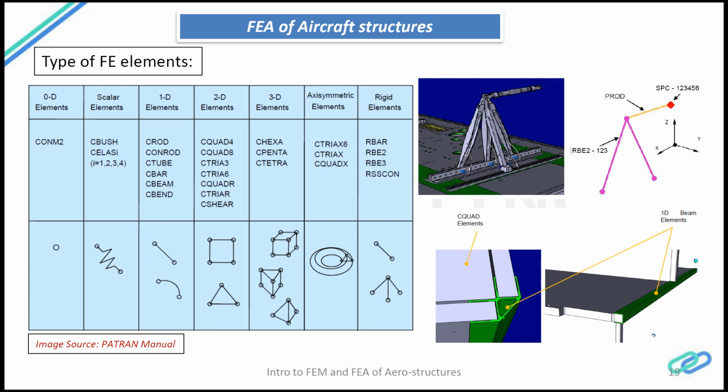What you are seeing is the top attachment, where you can see this is a top panel and there is a beam running throughout the length, which is a steel beam or a machined aluminum beam. And there is a series of struts, and finally this strut, going from the side struts, will be attaching to the aircraft interface, which is on the ceiling of the aircraft where there will be a lug. The other end of the strut attaches to that lug.